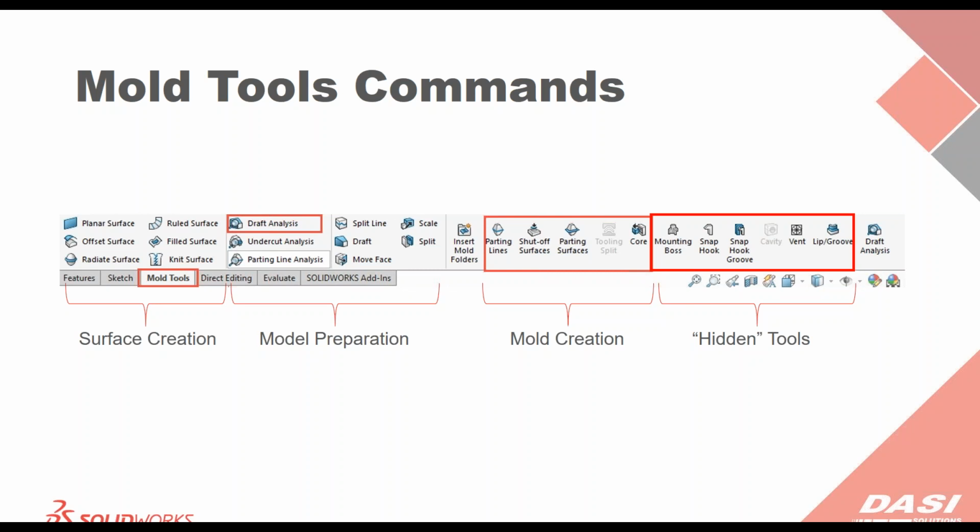Now, of course, you have to go into the customizing options, search for those tools, and then pull them out, drag and drop them, and add them to your command manager. But be aware they are there. You just have to look for them.